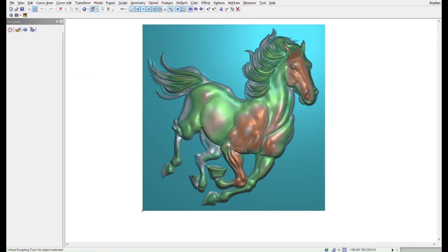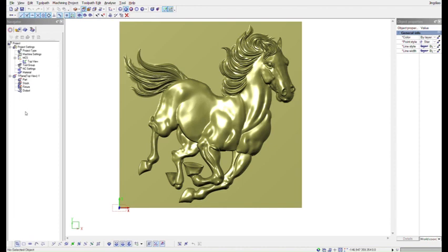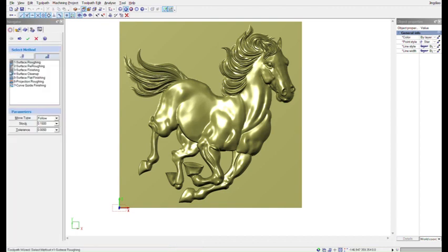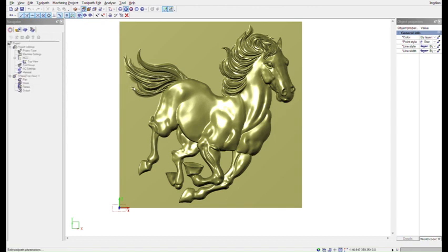So now you have to go to the tool path. There is an easy way to make it from the tool path wizard. You go to the tool path wizard and select surface finishing, the third one, and make it, and then it's going to make the projections in a parallel path. Okay, it is okay for this design. Some selections are there, that according to your experience you can select later.